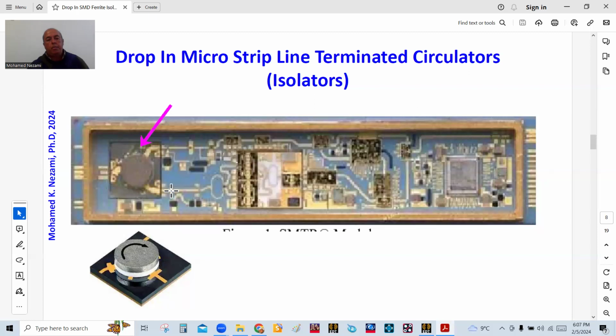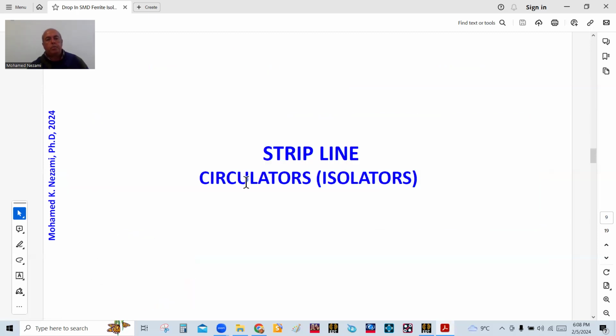You can see that the receive path is here, splits into these 2, or it could be a combiner in here, because you've got 2 die packages in here, and the signals combine and go this way, and then go out that way, and the receive path is going this way. Yeah, this is more like a low noise amplifier in here that goes out. So this is a full transceiver application. But you can see this here where the magnet is sitting right on top and everything.